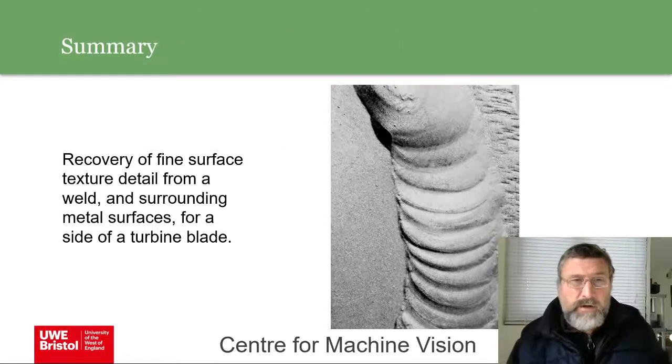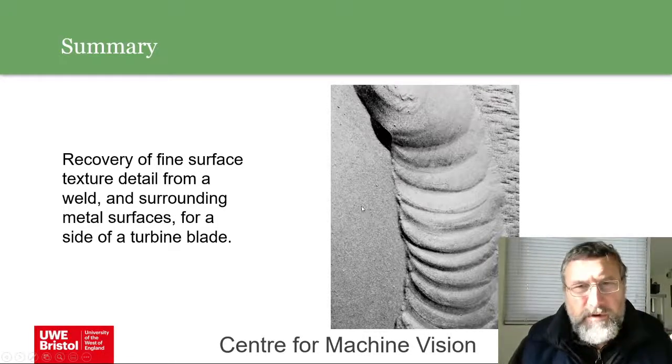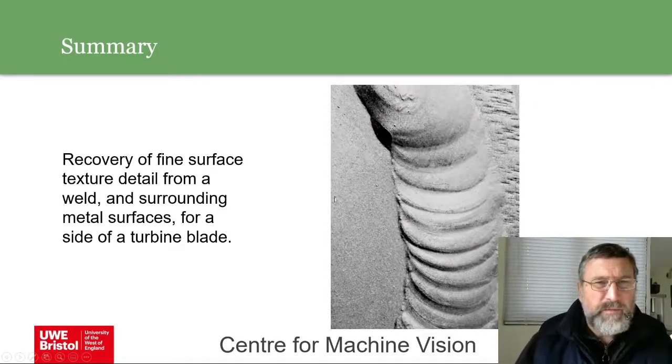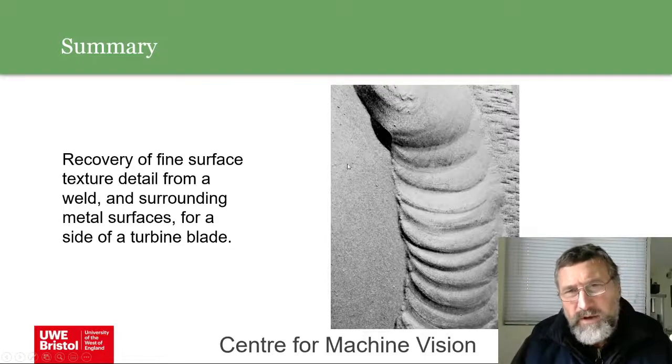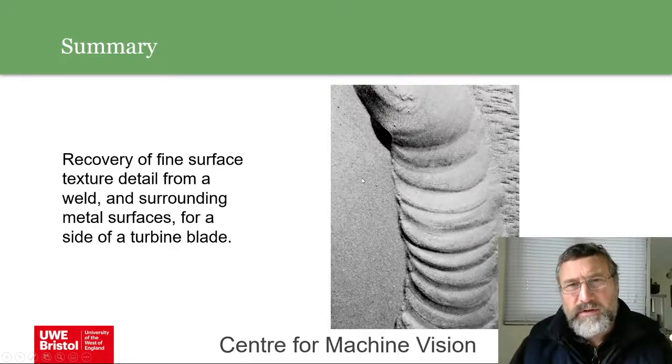Or turbine part. This is the weld. You can see it showing up quite nicely. Then there's a surface over here which has some kind of 3D texture on it, which is quite clearly showing up, and it looks like it's got a certain pattern in it. But over here, on this side of the weld, we're getting a smoother surface, which has a random but finer kind of texture on it, with also one or two tiny marks, probably speckles from hot debris coming off the weld.